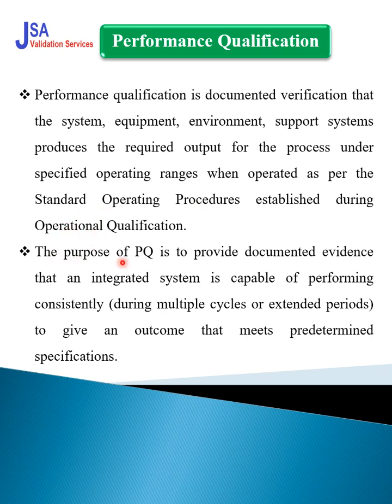Okay, the purpose of PQ is to provide documented evidence that an integrated system is capable of performing consistently to give outcomes that meet the predetermined specification. So in PQ we have to challenge the integrated system, not individual units. We have to run the equipment from the generation to the distribution. Okay, so we know that our integrated system performs as per the intended work.